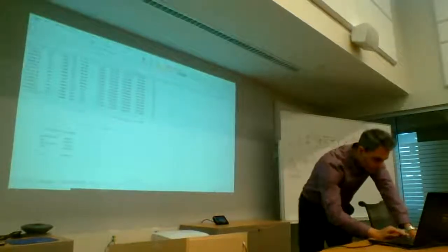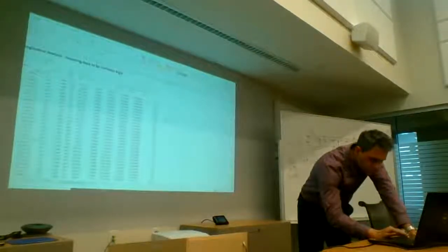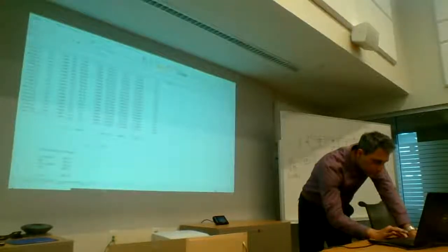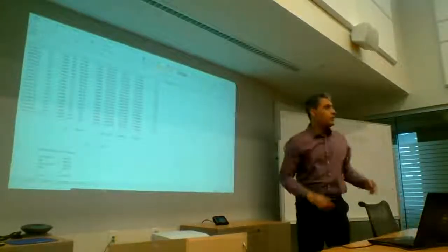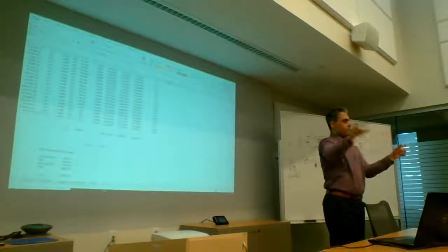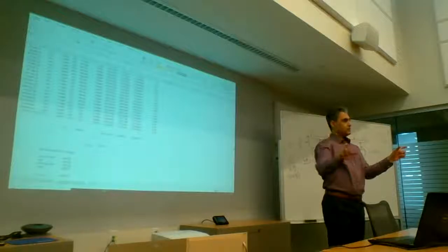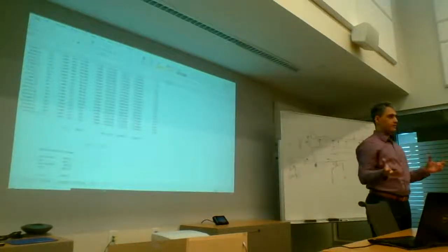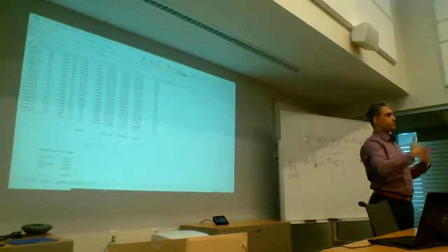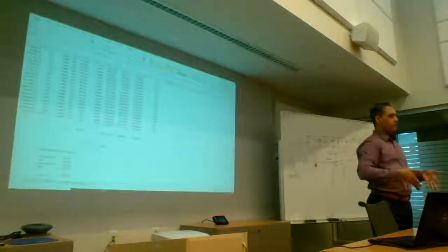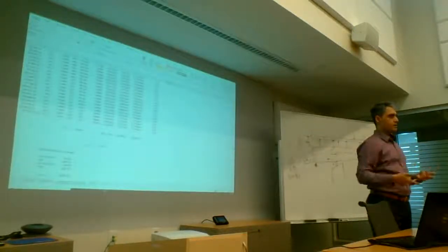How did you apply the mass at each location? Now the mass is assigned to each element. Is it the horizontal mass, or is it in both directions? Once you apply it, it acts in both directions, right? Yeah. Okay. Well, if you apply it in CSI Bridge or any other software, it applies it vertically, horizontally, and longitudinally and transversely.